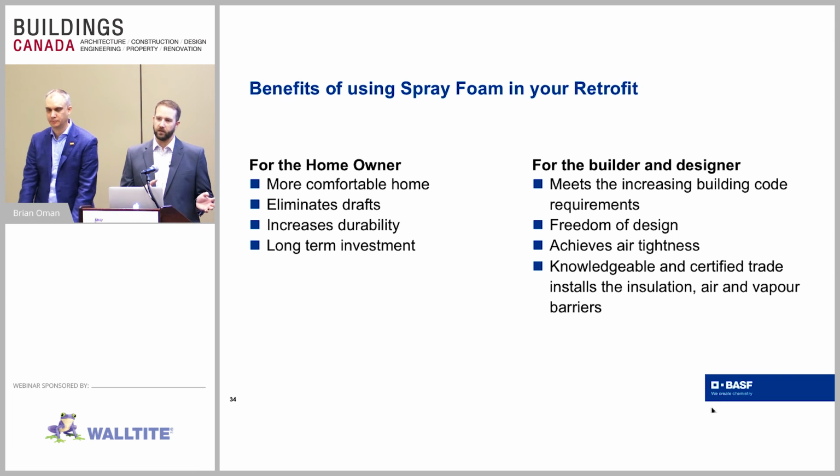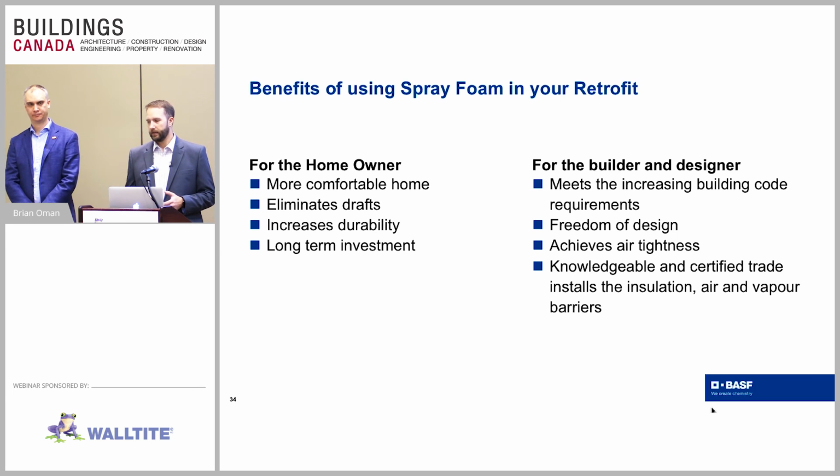If you don't have a system like that installed, you could put, say, a puncture-resistant polyethylene down. The only thing is foam doesn't adhere to polyethylene very well. So typically you would put the polyethylene down and then put a small layer of gravel over it to create a ballast for the spray foam to sit onto. You can do it multiple ways, but the majority of the time we see it done utilizing a drainage system to help diffuse the moisture potential and just utilizing the spray foam as the vapor barrier.